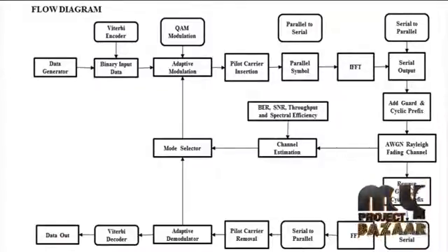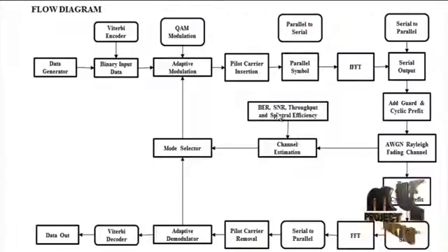Next, the OFDM receiver. The reverse operations of the OFDM transmitter process are performed. Removal of guard and cyclic prefix is performed, and the resultant signal is transformed by Fourier transform. Then demodulation is implemented using the adaptive modulator, and the decoding process is performed for the demodulated signal. Finally, the performance is analyzed. The final output signal is estimated over every channel and we analyze the performance: SNR, BER, spectral efficiency and throughput.